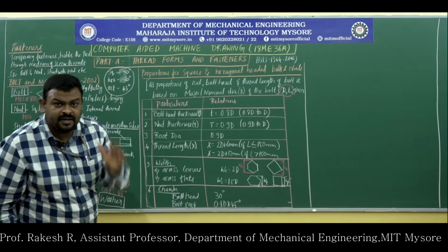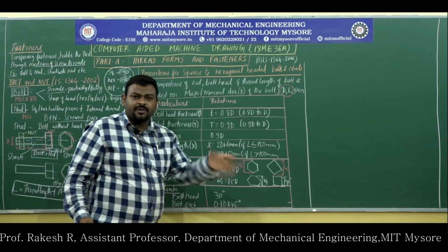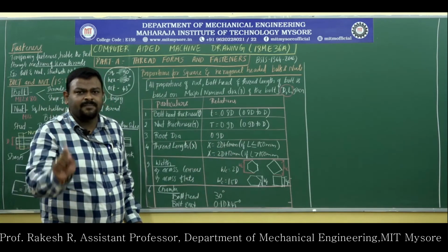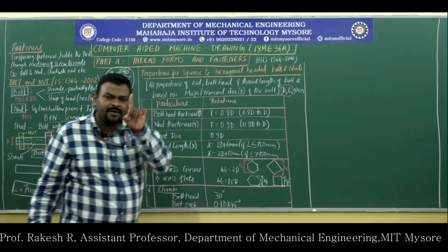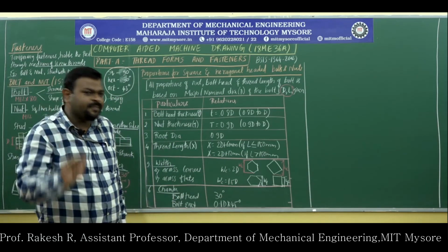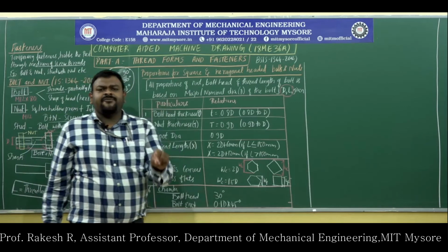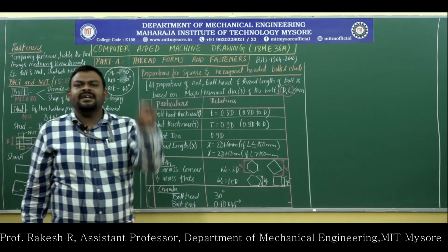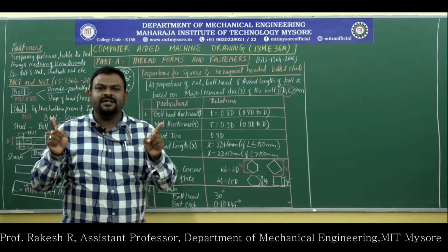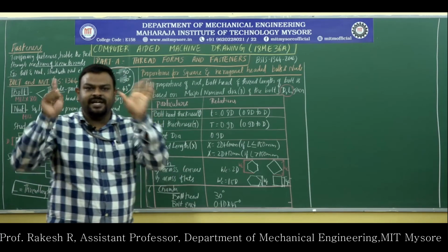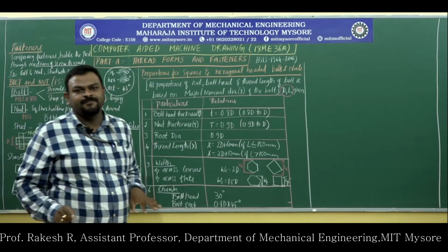Very important thing. If you change this, you are gone. Always remember one of the conditions; you need not remember both. Easy to remember: if the bolt diameter is D, then the width of the hexagon should be 2D from corner to corner.